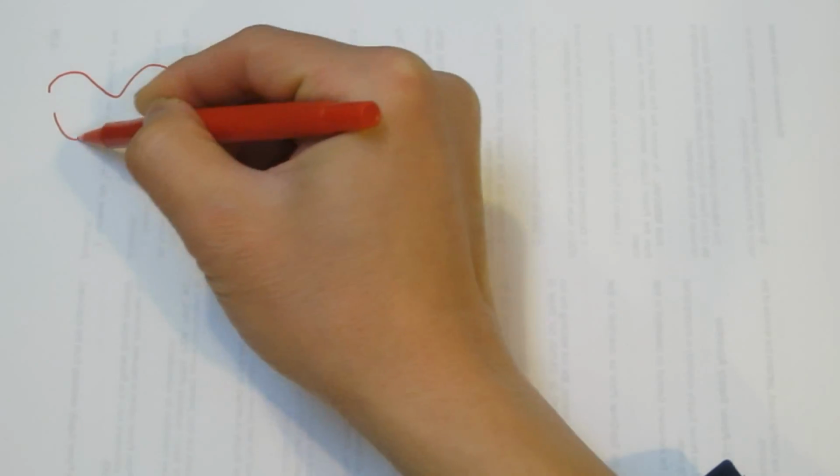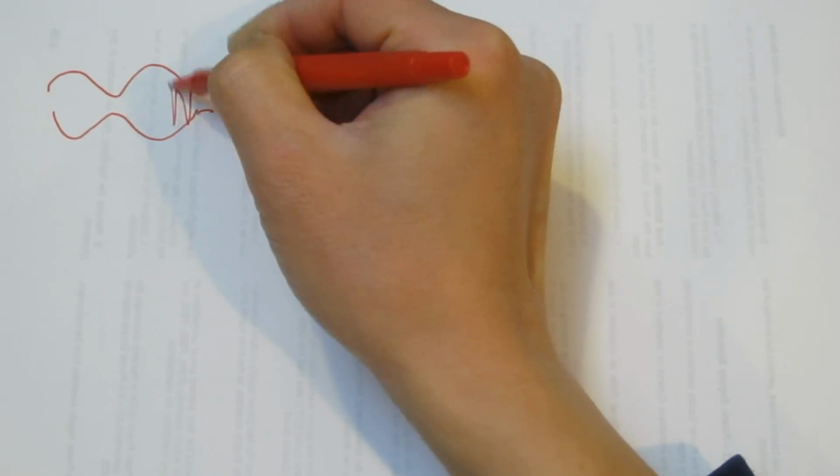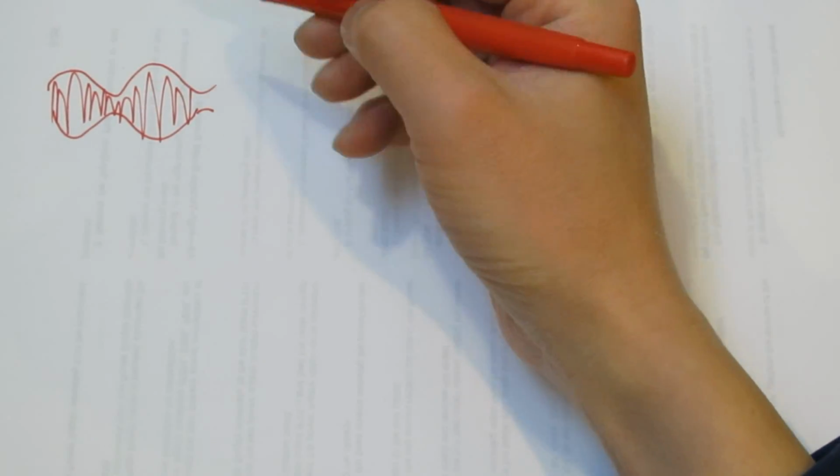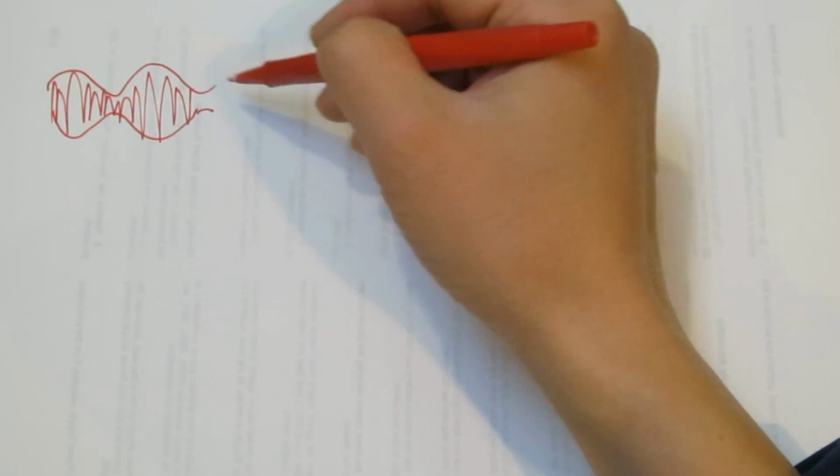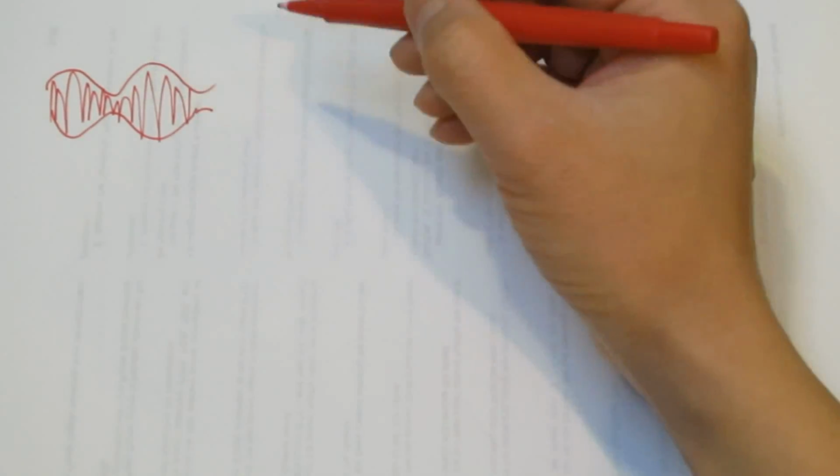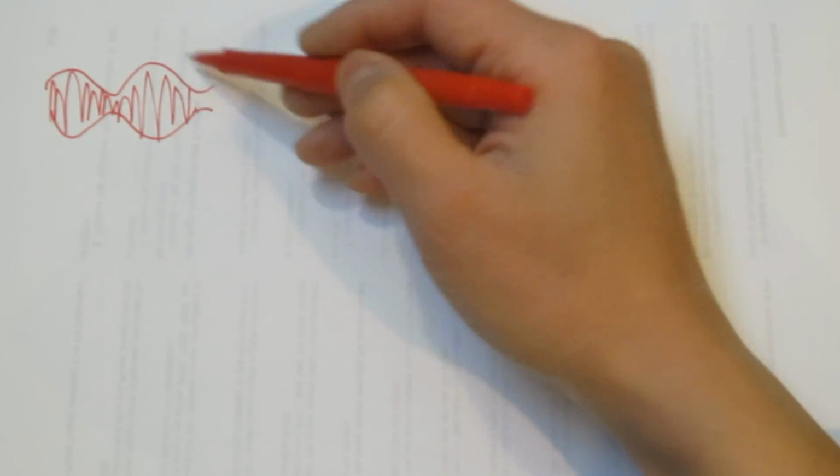So before we get started, I'd like to first go over some basic theory on how the demodulation is done using a spectrum analyzer. For AM signals, it's considerably easier and very intuitive. For instance, we have an AM signal sitting on top of a carrier frequency which is much higher than the actual signal being modulated with. Our goal is to demodulate the signal and retrieve the audio component, or the signal component, which in this case is the envelope.